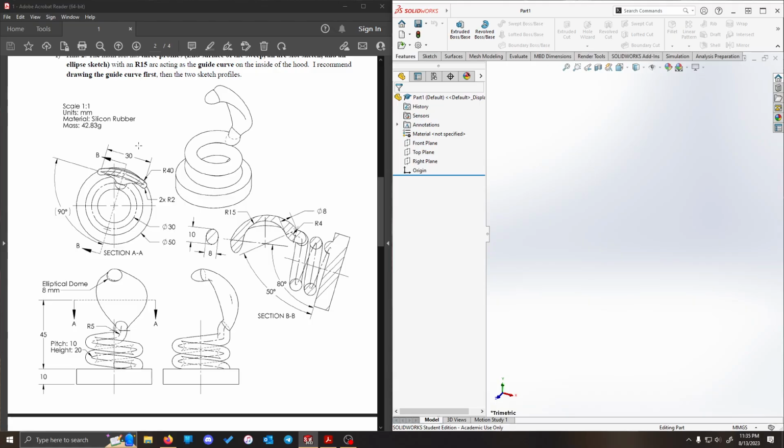So, all right, let's take a look at our thing and break it down. So we've got sort of this cylindrical puck down at the bottom that is a cylinder. That's going to be fairly straightforward, nice and easy point there. Then we've got a sweep that sort of follows our helix up, and then it's got these 2 elbows. So one of them is defined by the radius 5 we can see in the front view, and the other elbow is defined by the radius 4 we see in section B. So that's going to be our sweep path. We're creating a helix, elbow 1, then elbow 2, then we're going to stitch them all together with a composite curve and a circular profile sweep to get our geometry.